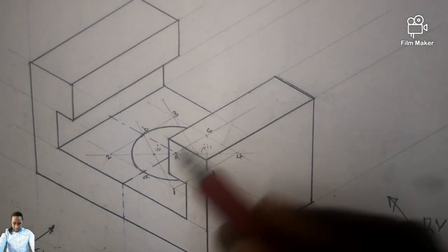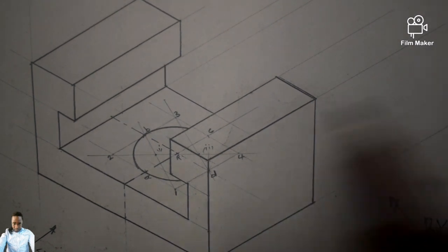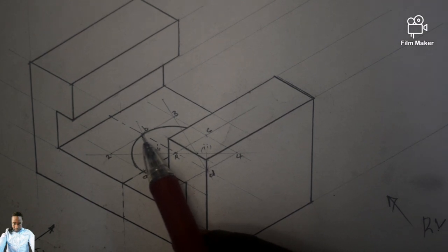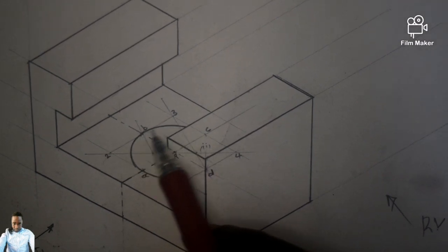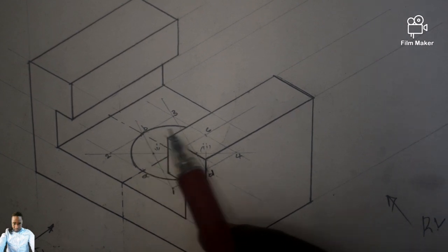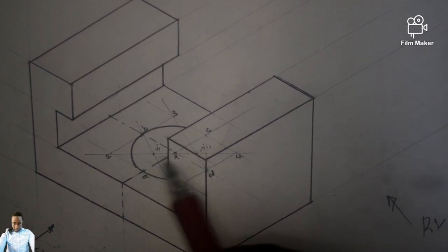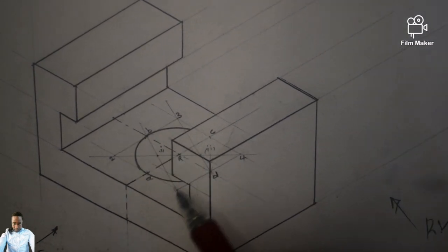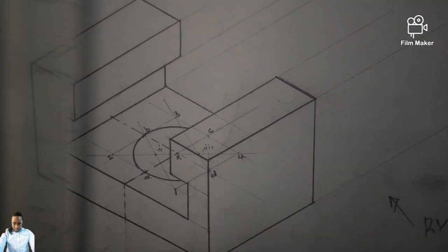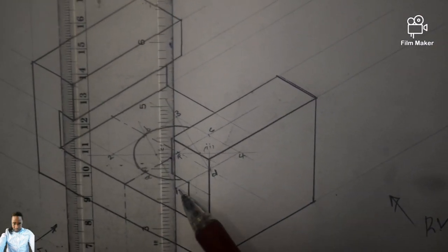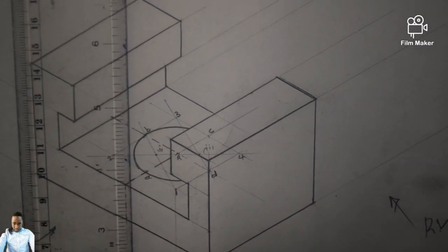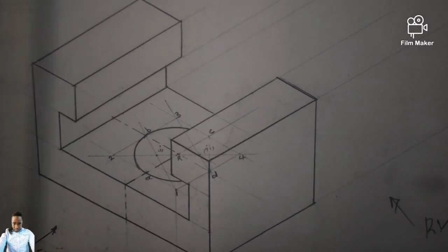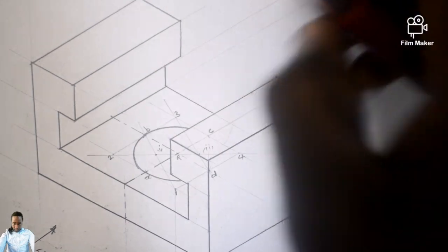We are going to project, because the thickness of the hole is going to be expressed by the parallel arc. The way you draw this arc, you are going to draw an arc that would be parallel to this one somewhere there. How did you draw this arc? You drew this arc by placing a drawing compass here till there, isn't it? So where were you placing the compass? At point 1. So it is the same point that's supposed to be taken vertically down. You understand? So now from point 1 till down there, you're going to record the dimension of the thickness.